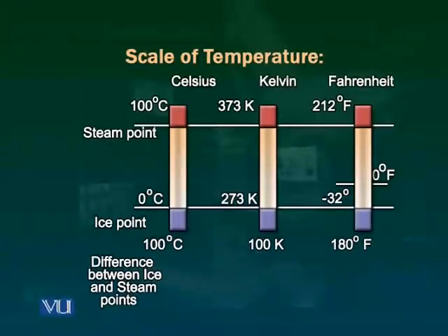Then we looked at the parameters of a liquid and glass thermometer. This is the lower fixed point, which is the ice point. This is the upper fixed point, which is the steam point. We divide this into 100 equal divisions, because we are assuming that the liquid in the glass thermometer expands uniformly with temperature, and therefore with a 1 degree rise, the level of the liquid should rise 1/100th of the length between 0 Celsius and 100 Celsius.